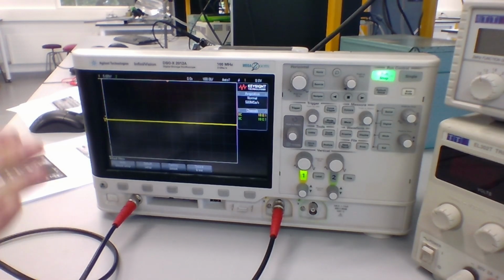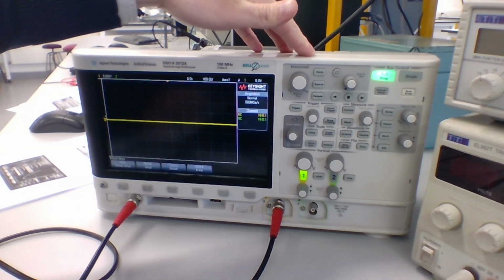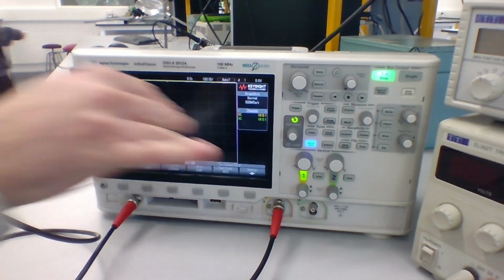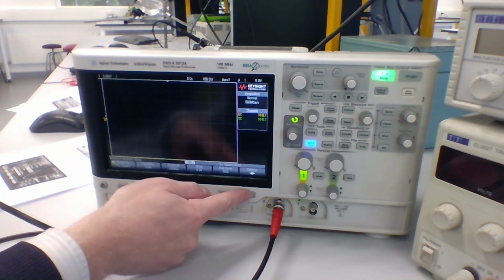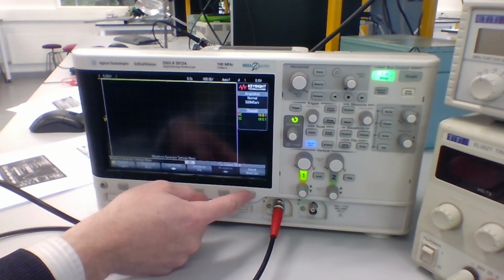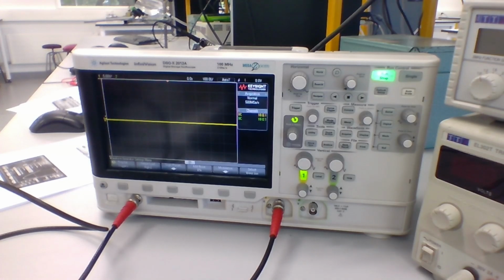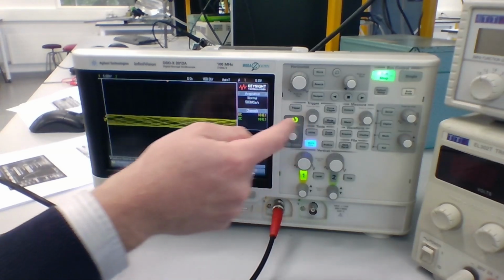We're then going to turn the wave generator on. So you'll see on the front panel here, there's an option labeled Wave Gen down here. If I press that, it will highlight blue, telling you that it is on and active. Then we're going to go to the settings here and press default wave gen. This just cleans everything up to a default setting, again, in case someone has gone and changed things. In this case, it sets it to a 1 kHz 500 millivolt peak-to-peak sine wave. To turn that back on, I press the wave gen button again to turn the output on.